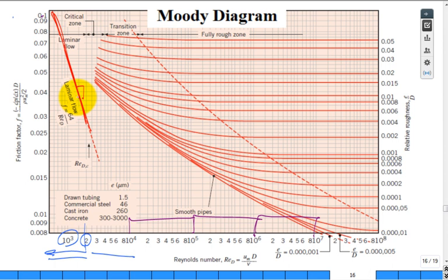Yes, these are all fully developed flow conditions. That's right. In most engineering applications, well, in the entrance region, you have a little more friction dissipation or pressure drop. So usually you just adjust a little bit for it. All right. Now, out here, you have turbulent flow.